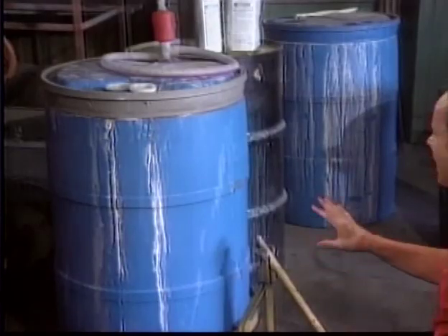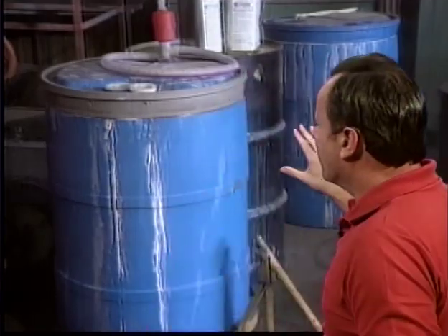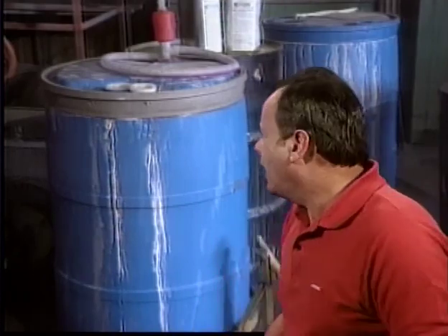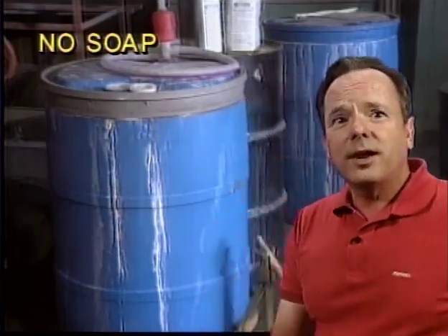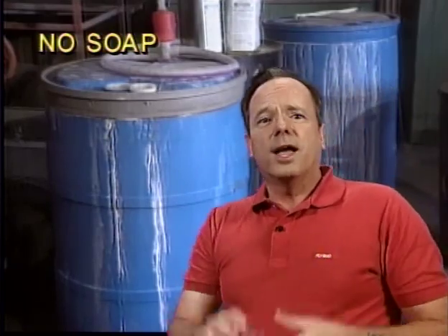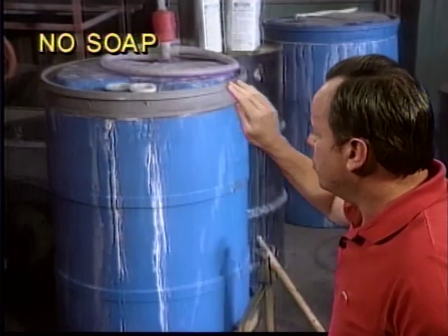Let's talk about cleaning engine parts. The thing you want to be careful of when you clean engine parts is what you clean them with. If you clean engine parts with the wrong thing, it creates problems when you reassemble that engine. It can cause oil contamination and foaming. So when you're cleaning engine parts, including aluminum and magnesium engine parts that they're going to ask you about on the test, it is advisable to avoid soaking them in solutions containing soap. So the answer is no soap. The reason is soap may become impregnated in the little metal pores in the metal, and cause engine oil contamination and foaming.